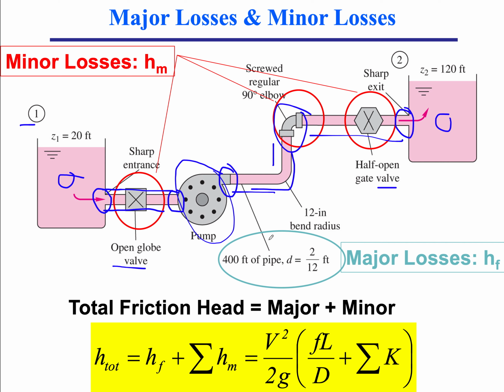And these will introduce friction to our pipe. Remember, so far we have said it's only the pipe, the pipe of length L and diameter D that's going to create friction head loss in my system. But not only. In fact, these pipe fittings are going to generate quite a bit of friction head loss. And we call those the minor losses, the minor friction head losses, as opposed to the major friction head losses associated with straight pipe segments.